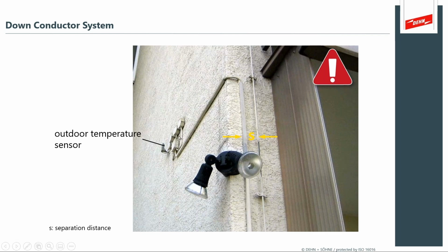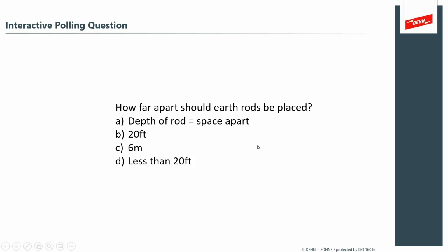So you might have radios, temperature sensors, and in this case, emergency lighting and outdoor lighting. You're injecting lightning currents directly into an emergency lighting system that is in fact required to have surge and lightning protection. So you've just introduced it to the most vulnerable emergency system.